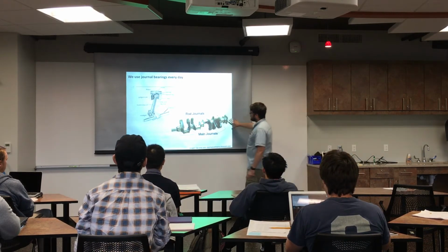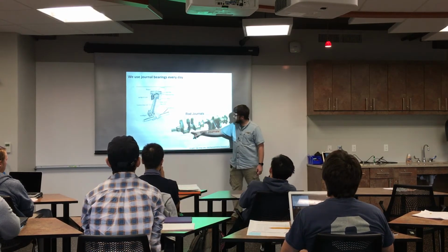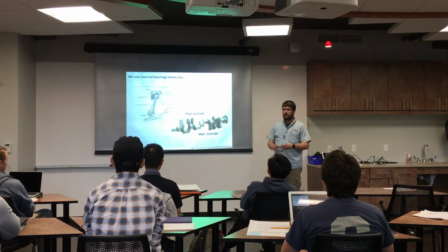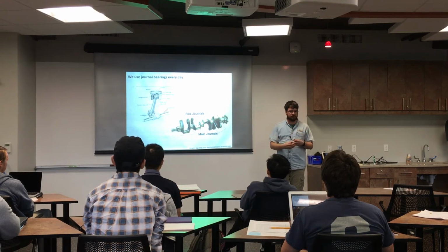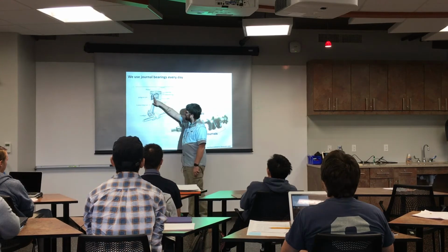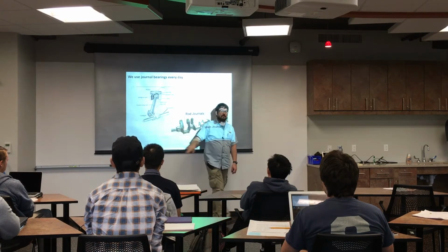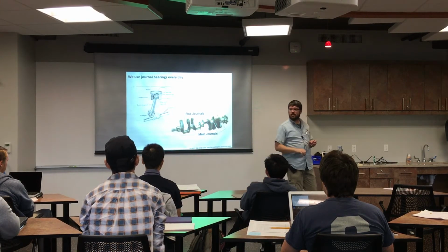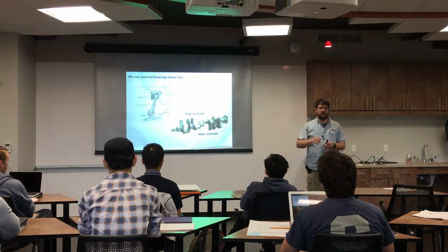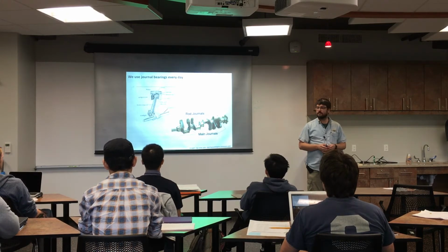This is the crankshaft, which is where all of your pistons mount. And these spaces where the bearings are called the journals. You often hear people grinding the journals or redoing the journals if they have some damage to their engine. And you've got the piston, and it's connected with this connecting rod down here, and here's the actual bearing. So journal bearings let the pistons move around the crankshaft. Very low friction and very low wear. Your car lasts for 100,000 miles at thousands of RPM, right?